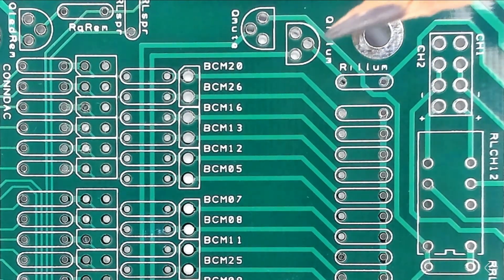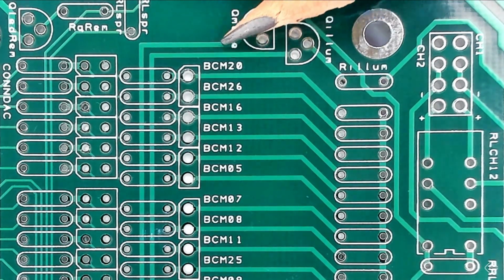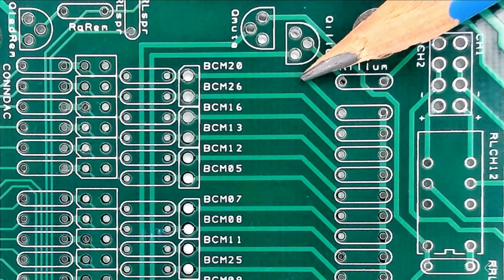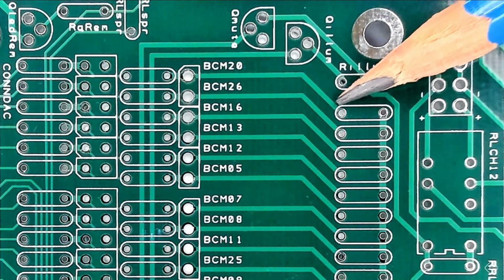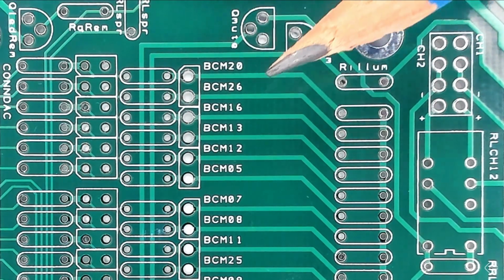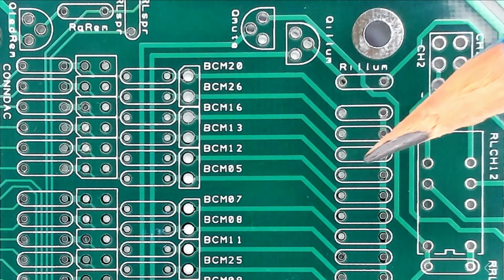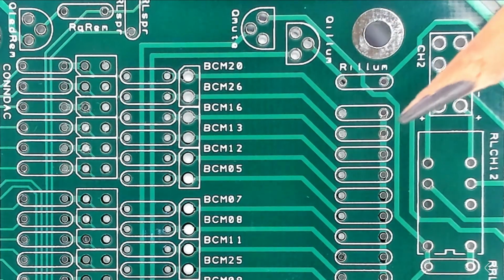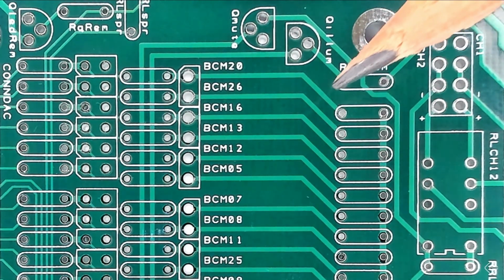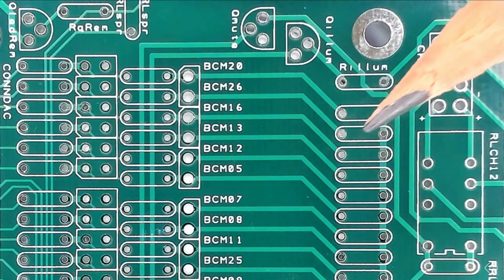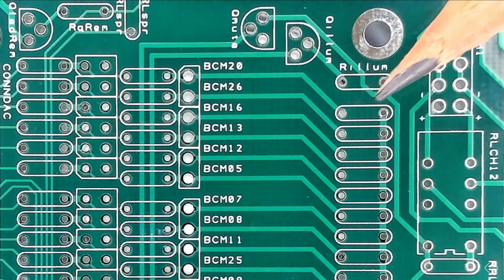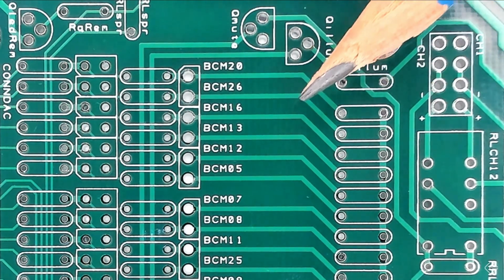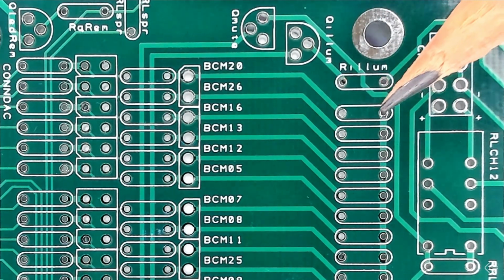You can clearly see where the traces are. You see the dark green background, and then you see the lighter green shade where you see these lines coming in. Those are the traces, and those are the equivalent to the wires that we have. So these connect all of the different pads that you see on the circuit board. The pads are typically outlined in white, but within those white areas, you can see every single one has at least two of these metallic pads, and those two metallic pads are where the component sits.